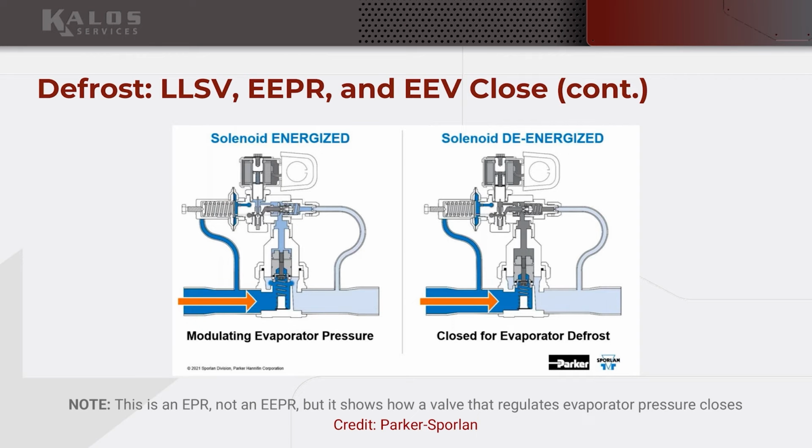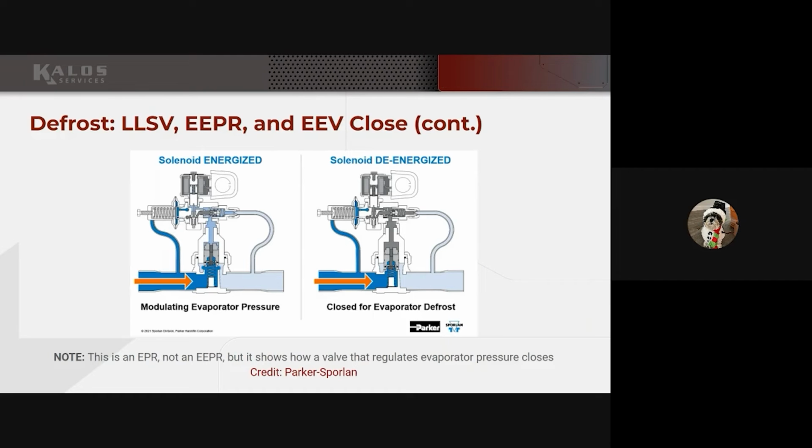So the liquid line solenoid is sort of like a reversal in how we're thinking about it, at least when controlled locally at the case. When we're talking about out at the rack house, I believe I was told that those are different. But mechanically, the liquid line solenoid at our cases is a normally closed valve. Right. But when it's, the circuit would be open, correct? So it's sort of opposite. So like when we're energizing the liquid line solenoid, we're closing. No, we're opening. Sorry. It's hard to.